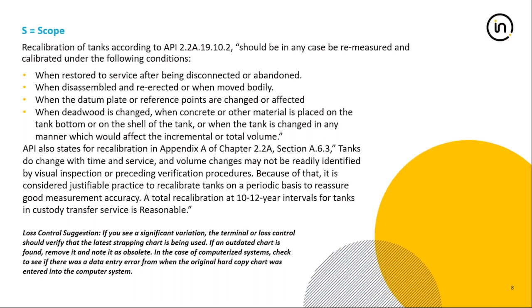When you move it, you're going to create different discrepancies in the walls of the tank, because you're not going to be perfect in your construction and there's going to be a little bit of an offset, or you're going to maybe shift it a little bit on the vertical axis, and all of that is going to impact the accuracy of the level measurement, which ultimately is going to impact your inventory measurement, or the actual volume that you are holding within the tank.